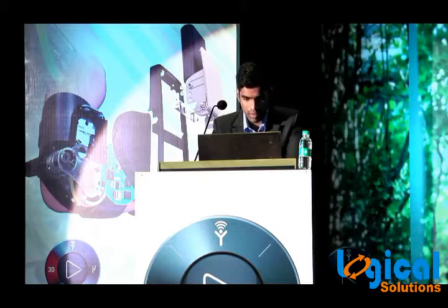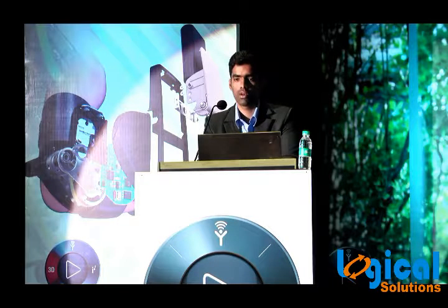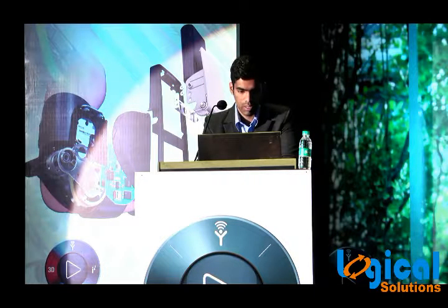This is the part which I am going to take as an example. I am going to the sketch mode, onto the face, and now here we have a direct option, whatever you want. This will be at your mouse button, at right click, and you can directly select from here. Selecting the straight slot, I have created a straight slot like this.